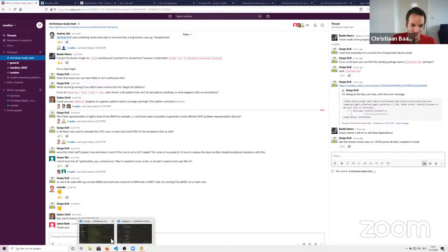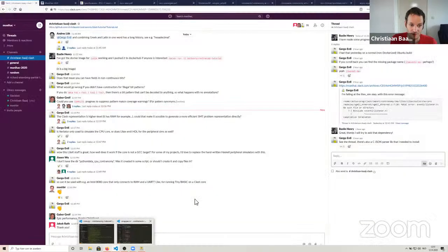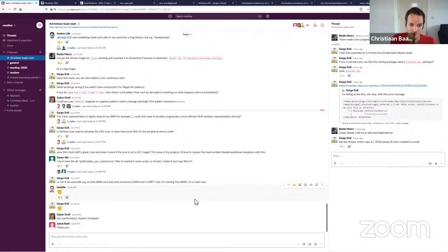Oh, I think I see what you're going to show me. You're basically going to tell me that currently you get 1 bit of output from the formal verification, whereas if you generate it from Clash, you could get meaningful failures. Yeah, you get meaningful errors, like it's saying this line in the Haskell code. Now the tool will complain about the generated Verilog, and then you have to hopefully figure out how that translates back to your Haskell.